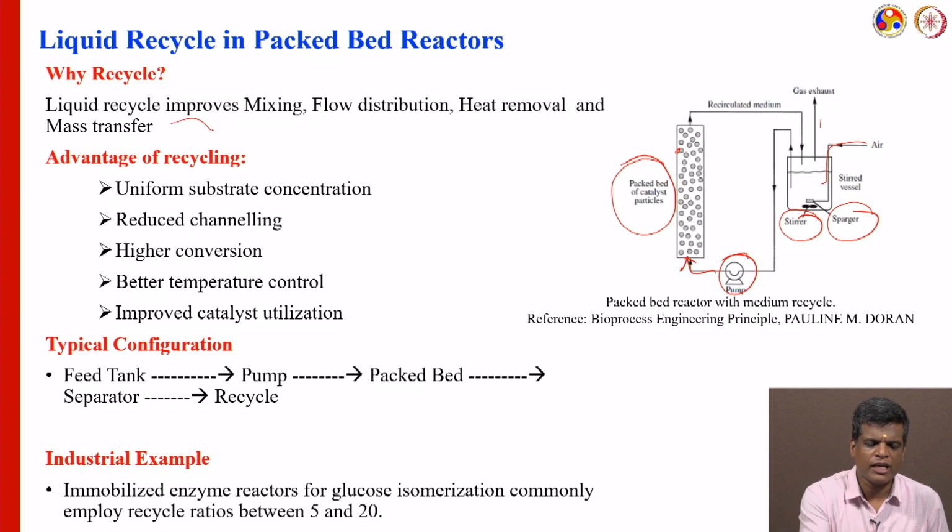The liquid recycle improves the mixing and gives complete flow distribution, and sometimes heat removal, and increases the mass transfer. Mass transfer increases because of the higher concentration driving force. In the same way, mixing will also improve. So, what are the advantages of recycling here?